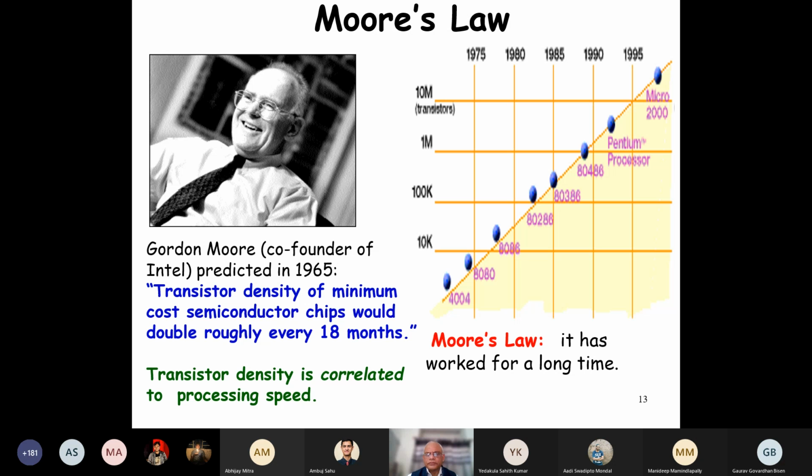Hello, sir. Can we do it using pipelining so that we can reduce the critical delay, so that we can improve? Pipelining does not need more transistors, Sohini. Let me just clarify. We'll see pipelining in this course, but pipelining is about keeping the transistors more busy. It is not about requiring more transistors. So I don't think that answer is correct. Let us see. Please watch out in this course as we proceed.